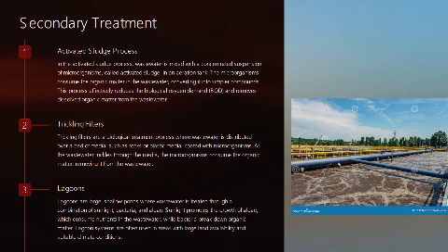What then is the secondary treatment? And 2 things that you have to really recognize. The first one has to do with the activated sludge process. In this process, the wastewater is mixed with a concentrated suspension of microorganisms. And this might sound weird to you, because we want to make the water pure. Why then are we introducing microorganisms? Now, this concentrated suspension of microorganisms is called activated sludge, and it is put in an aeration tank.